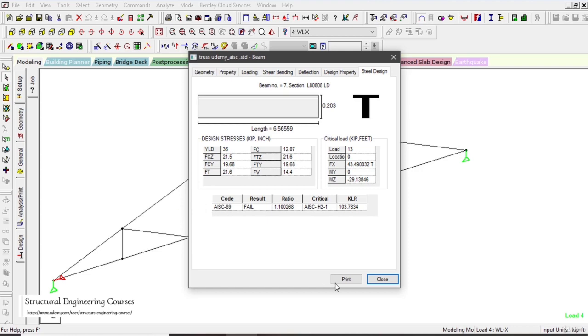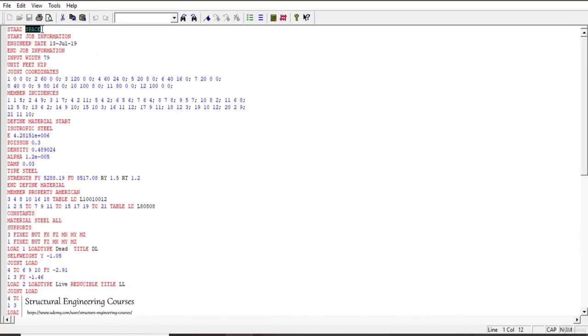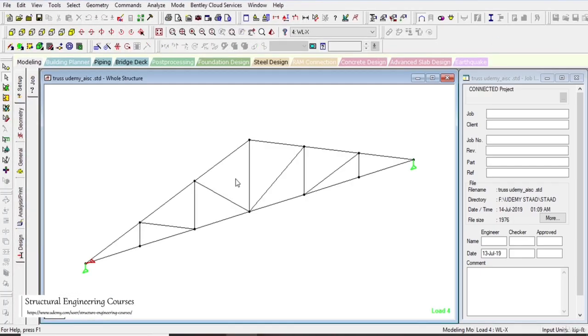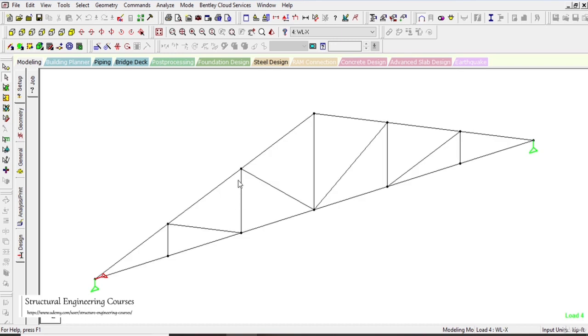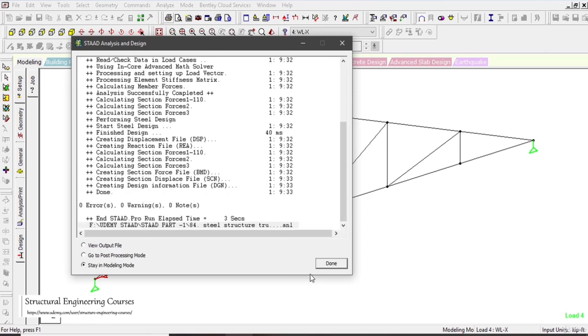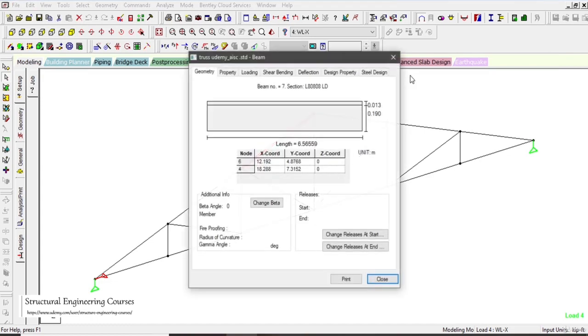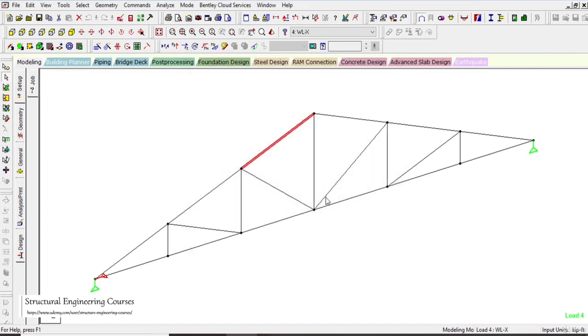But basically the problem is that the reason this bending moment value is coming is because we had applied the UDL on these members. So when we were doing the STAAD truss analysis, at the back end the STAAD was calculating the nodal loads by itself. So that is the basic difference. So I shall always suggest that always enter the STAAD truss option here, and do check the behavior and do check the results.